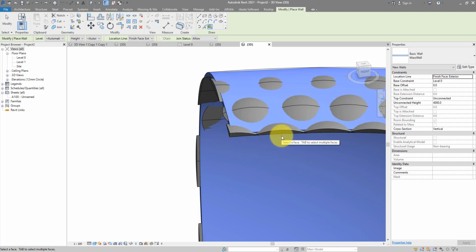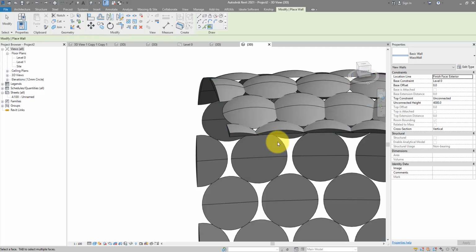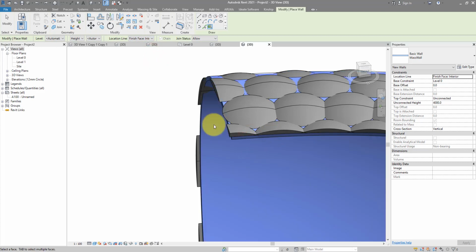And you can see the wall seems to be clashing a lot with our panels. Let's undo this. The reason was that the face we used to generate the wall was its exterior face. This is a bit of a fuzzy concept because sometimes if you want the wall to look right when you create it by face, you need to change this to something else. So instead of exterior, I will need to do the opposite, and that's interior. Let's pick the same face again. And this time it's correct.